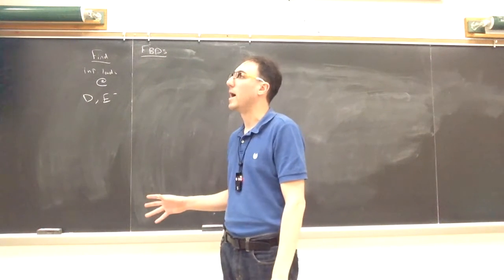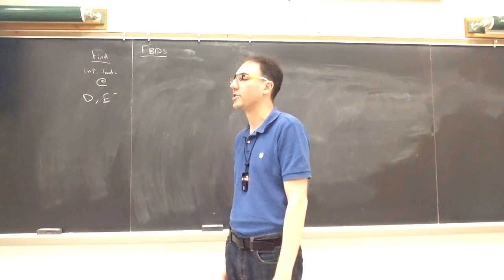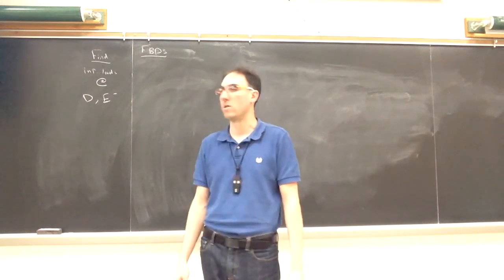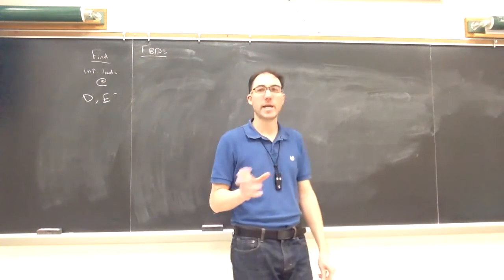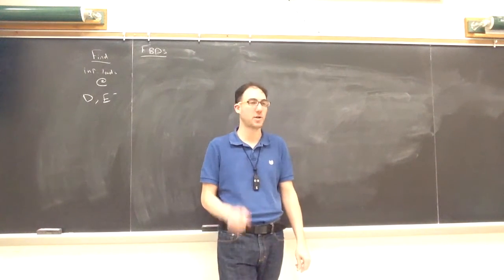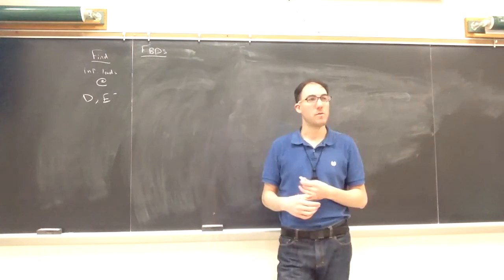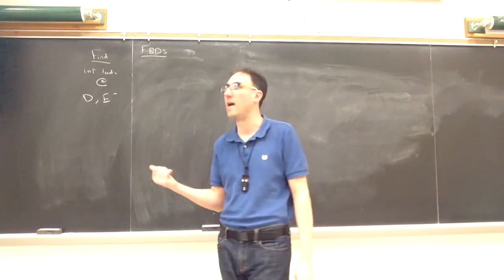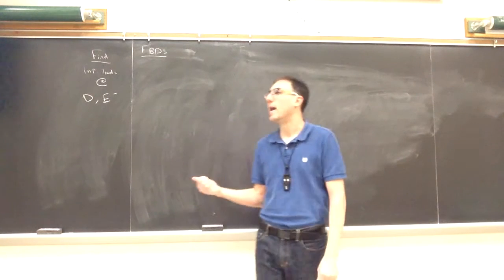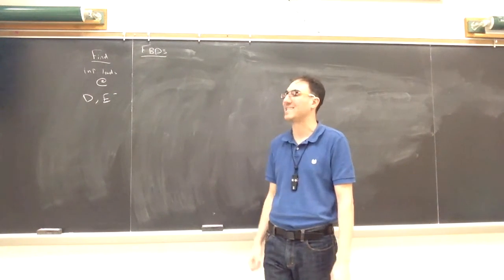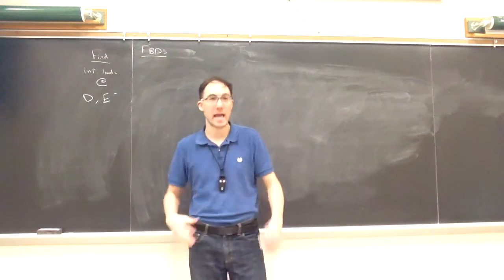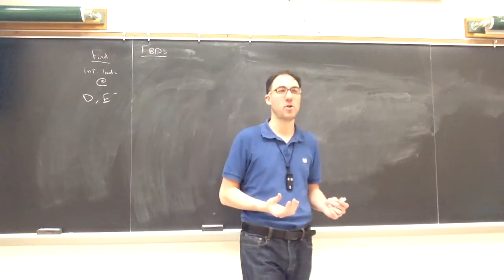Looking at this, we have a built-in connection at A, or a wall at A, a fixed connection. At C, we have a roller. So externally, how many reactions does this object have? How many unknowns externally will we see here? Right, we have 4, because at the wall we'll have an x component, y component of force. We'll have a moment at A, and then we'll have a y component of force at C. So there's 4 external reactions happening here, which makes it externally statically indeterminate.